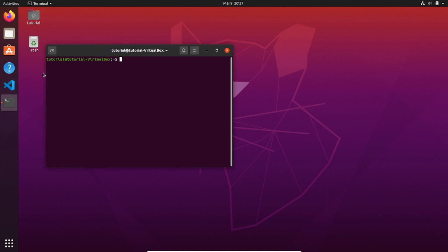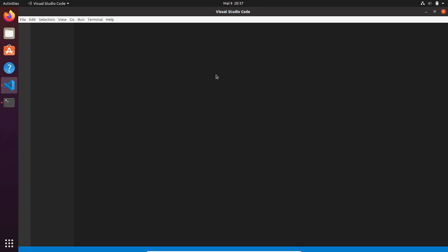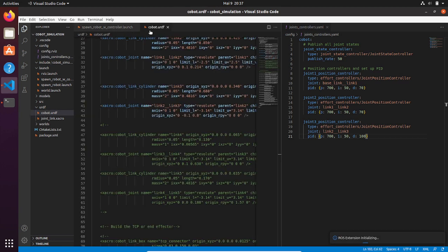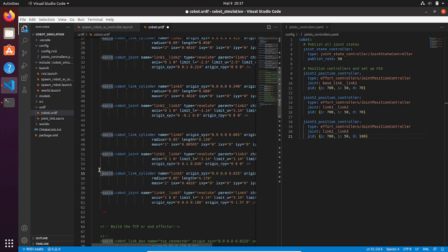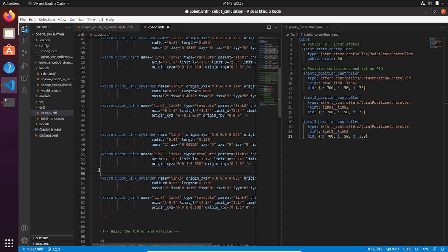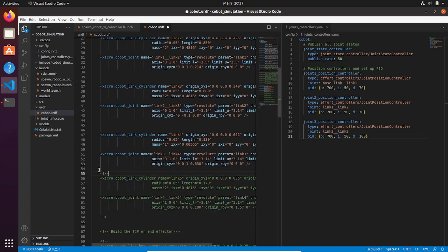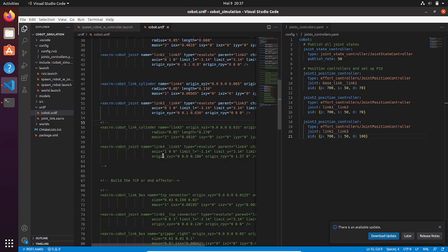Hi roboticist! In this video we are picking up from the last time and we are going to add the link 4 to our robot. So first of all, let's go to the URDF file and uncomment the link 4 and the joint that attaches the link 4 to the edge of the link 3, named link 3 link 4.